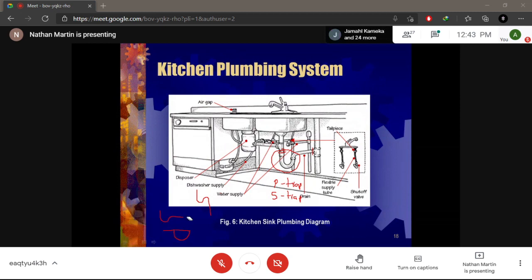So these are the different types of traps that you will use. And then somebody tell me the mounting height of your trap. Well, the connection in your wall here, your drain connection from the floor, your typical mounting height. And what is it? No? Think about it. 2 feet. All right. So the mounting height of the trap from the floor is 2 feet, right?